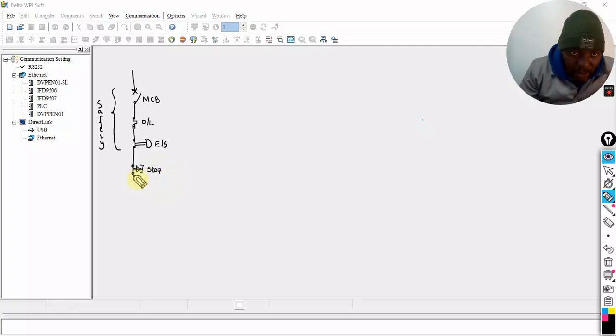Now we want to start our machine. That is a little bit too long. I don't think I've got the space, but anyway, let's try to squeeze it. The start is an open, again a press and release type, the spring type, which will spring out. So that's our start. Normally we will start what is called a main contactor, the main contactor coil.